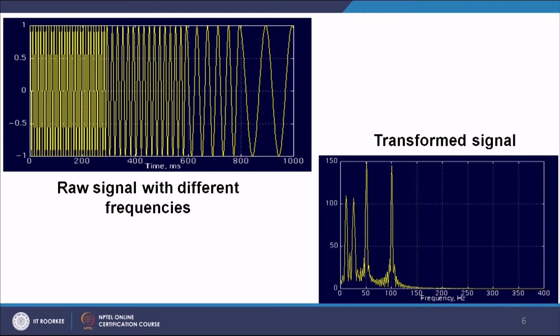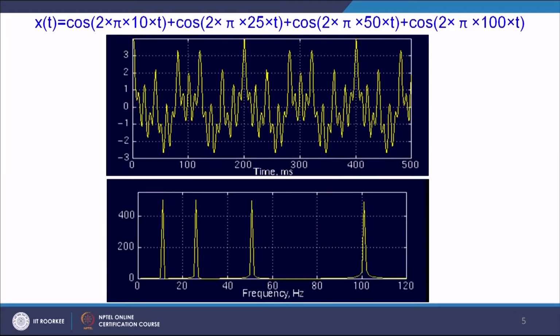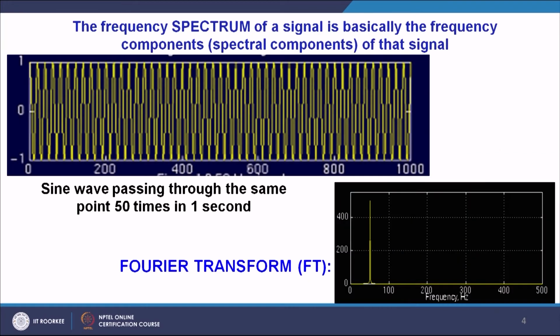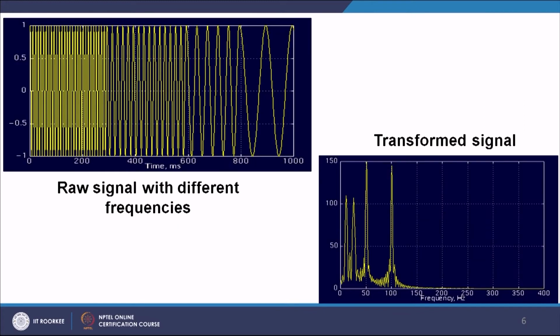So, you see what we have done, we have transformed that signal into an FFT curve. You can find some peaks coming like this. By comparing this one with your previous signal, here we have got a peak at 50, but subsidiary peaks are also obtained at 100, and here we are seeing something around 25, 20, something like that.